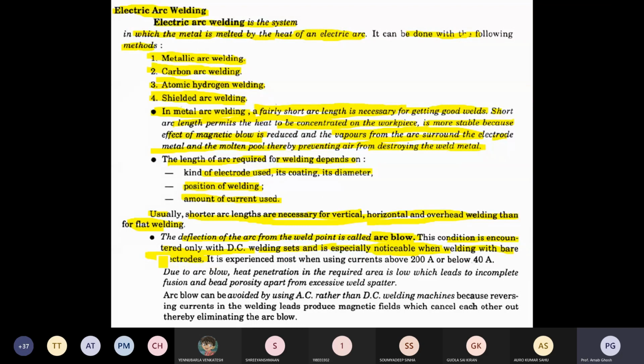Normally there are two types of electrodes. Those who are very expert at welding use bare electrodes. But with bare electrodes there is a chance of shock. So if you don't have any experience with this work, you should not use a bare electrode. You have to go for flux coated or insulated electrodes for prevention. But flux coated electrodes will definitely be costlier than bare electrodes. The welding experts normally use bare electrodes for commercial purposes.